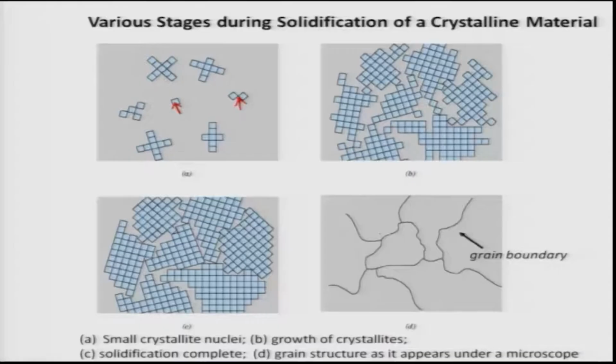Just to give an idea of the bulk of atoms in the liquid, they have a random nature and will be moving in the liquid randomly. Only a few of them come and join to form a cluster. Therefore, only a few of these atoms are well ordered, with crystalline order present. Thus, the interface between these well ordered atomic clusters and the liquid is diffuse.